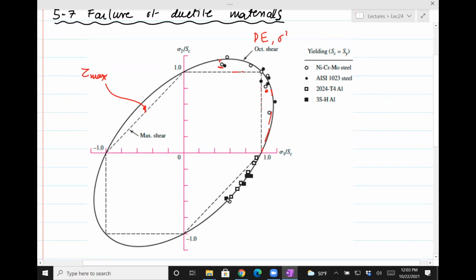So really what this is saying is you better be a little bit more conservative. You better apply the factor of safety when you design things. Don't really use the shear strength and this theory to design a material. So always we keep some factor of safety, so our actual envelope is actually going to shrink by that amount.